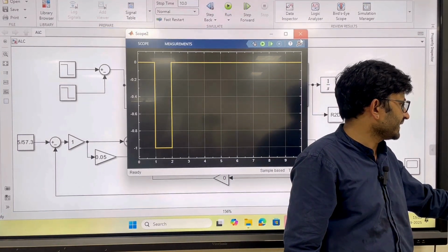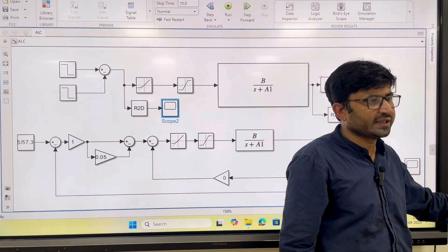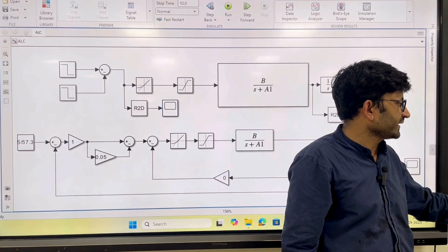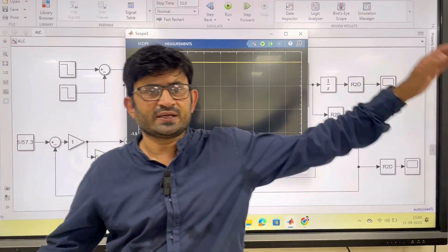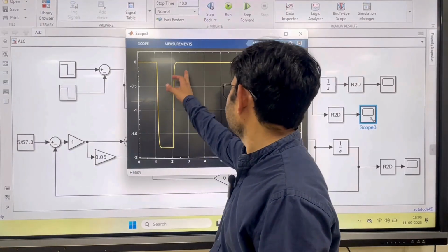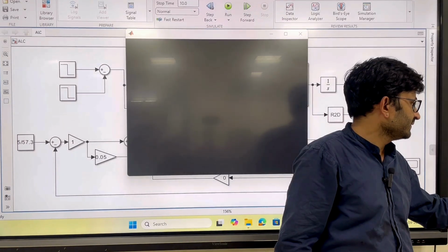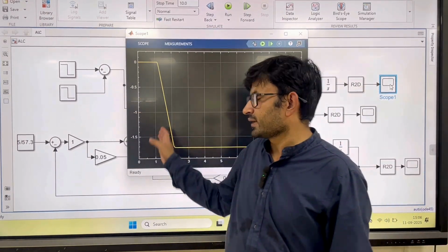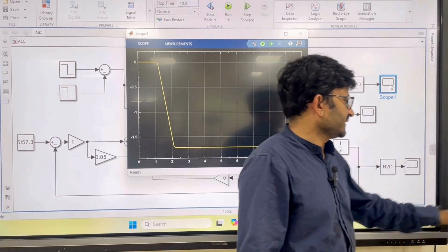So this part is clear, right? The aileron you have given. And when you integrate P you will get the roll angle, right? First you will see the roll rate. Obviously when you bring back the aileron, after some time the roll rate will become 0, right? Now it is 0. What will the angle be? Some constant value will be there, right? So this is the roll angle. If you give more aileron, naturally more angle will be there. Now this is one case.